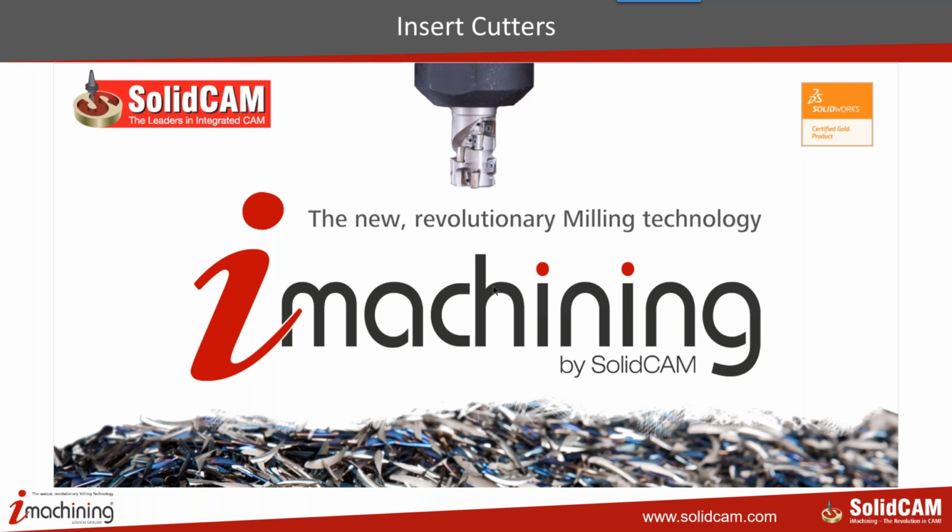Sometimes a slightly different rake angle, for example, on your inserts can mean that using the cutting conditions recommended by the iMachining wizard for the imported tool could cause harmful chatter when used with the local tool. If that tool is needed for a long production run and the price difference is significant, your best course of action is to use SolidCAM's certification service, which would result in that local tool being added to the new table after being calibrated and certified.